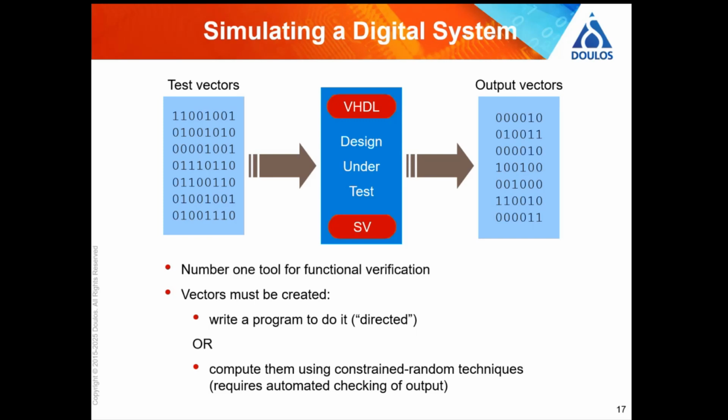And a basic test bench would probably be what is called directed. A directed test is where you decide what inputs to give to your design under test, hopefully in relation to the specification. So the specification might say, specification point 1, 2, 3, it must do this when this happens, and you would write a specific test to do that, and that is called a directed test.